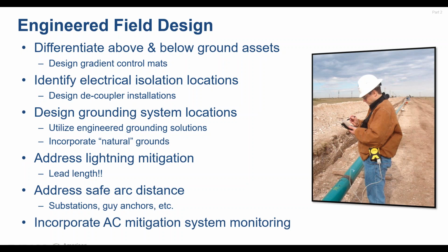As an example, the last point there is incorporating monitoring. We referenced this in our prior presentation, and as we move forward, it's extremely important that you design monitoring into the AC mitigation design, because once again, we're going to stress the dynamic nature of this multi-headed beast. We know it's going to change. We know it's going to morph into some other shape. So the monitoring facilities become critical as we install the mitigation system, so that we can constantly monitor this and get a great handle on what's actually happening real time in the field.